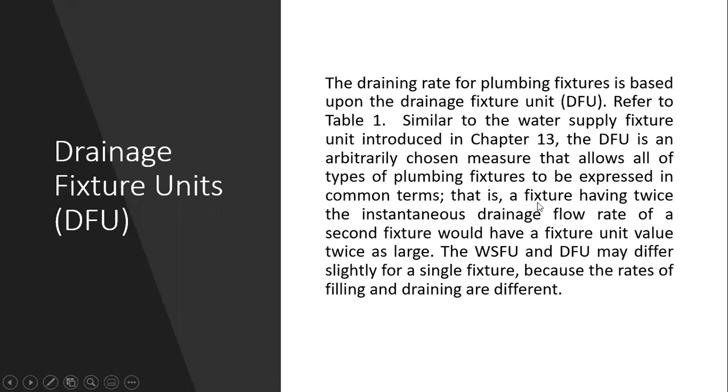That is, a fixture having twice the instantaneous drainage flow rate of a second fixture would have a fixture unit value twice as large. The WSFU and DFU may differ slightly for a single fixture because the rates of filling and draining are different.